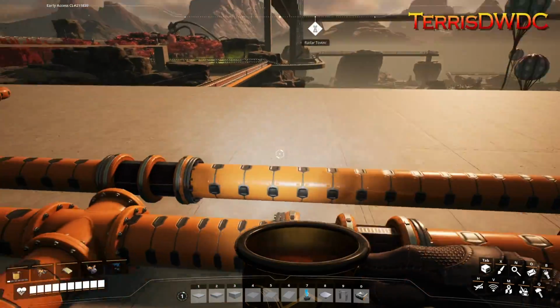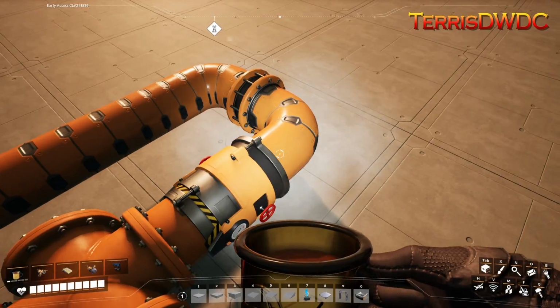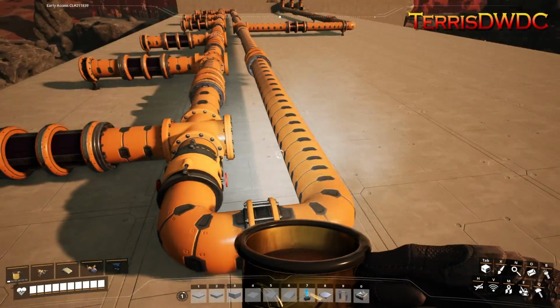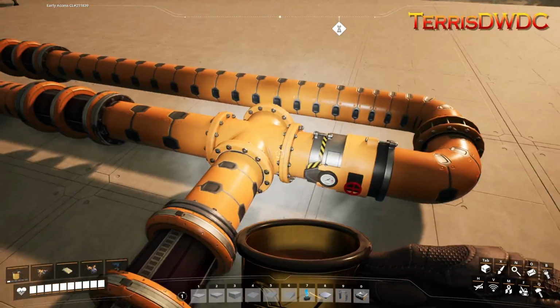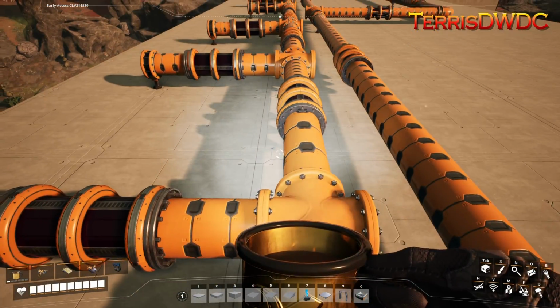Same at this end. This fluid is coming this way. Once it goes through that valve, it can't go back again. So we're not dealing with any more slop going back and forth. It's basically forcing that fluid to keep moving in this direction.